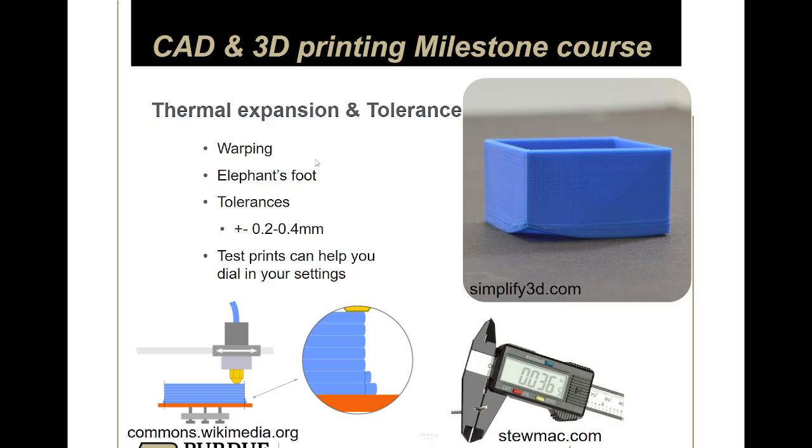The other thing that could contribute to warping is, again, the geometry. So corners, sharp corners specifically, create higher stress concentrations. You can see here, this corner of this cube shape kind of pulled up, right? Those corners have stress concentrations that will curl the parts a little bit more. If you make the part rounded with something like a fillet, that stress concentration is spread out over a larger area, so it's a little bit less prone to warping.